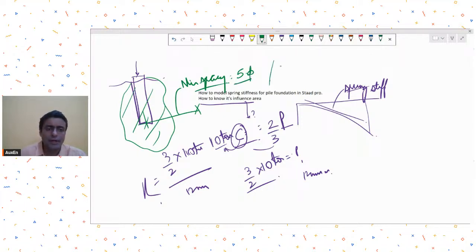If we have an end bearing pile, usually we try to go for 2.5 to 3 times the dia as the center to center spacing between the piles. So in order to avoid two piles which are quite close by from influencing each other, we try and maintain some minimum distance between them. Okay, all right. So this was his question.